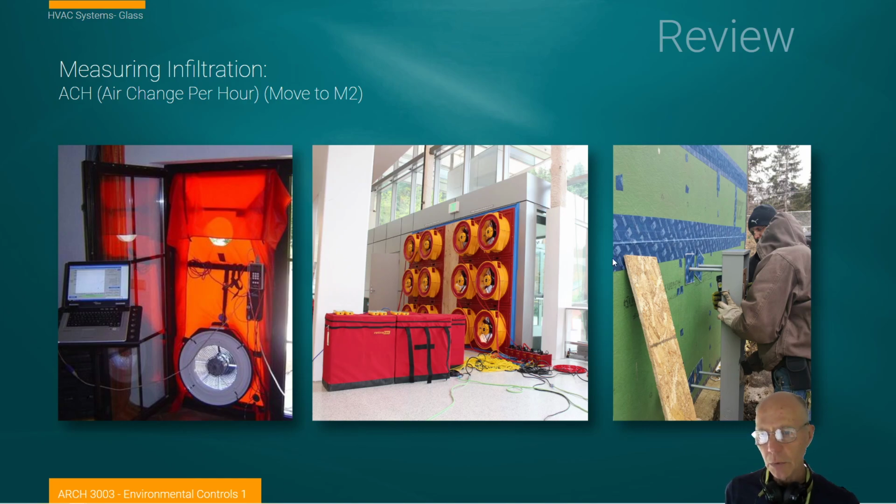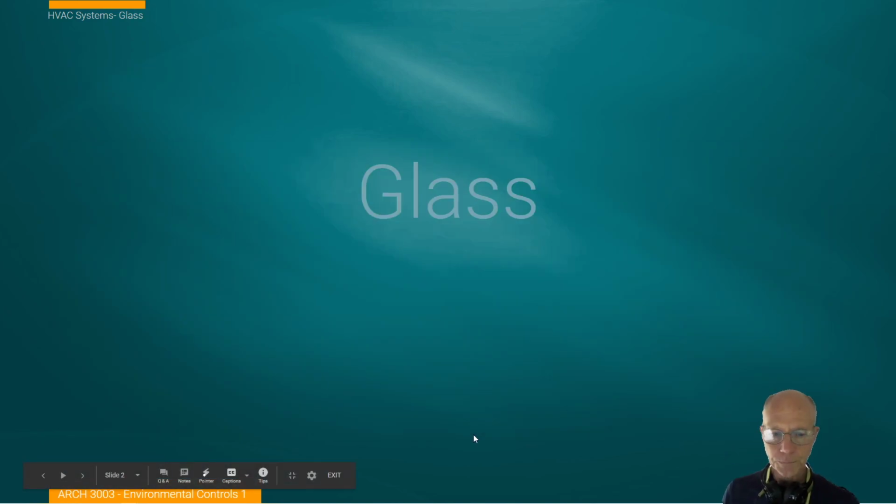So here we have this blue air barrier tape being applied. It looks like it's applied anywhere there may be breaks in the system, whether it be the application of fasteners, or in this case, they're putting a panel box on, and it looks like they're trying to be very careful about sealing around the passages of those. So today, this idea of controlling unintended air entry into the building, air infiltration, is really important, and I wanted to just cover that a little more with you.